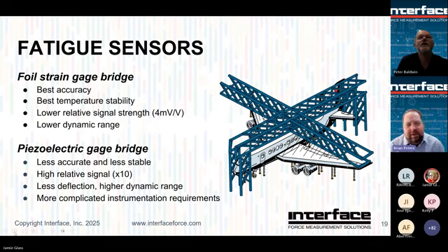I will touch on that: Interface's sensors, for the most part, rely on foil-based strain gauge solutions. There are other options when it comes to force measurement, specifically around dynamic loadings. Often piezoelectric load cells are used for, I would say, impact type loading. But as we're going to explain here, foil-based strain gauges are still very well suited for very dynamic applications as long as you understand the limits and how to work with them.